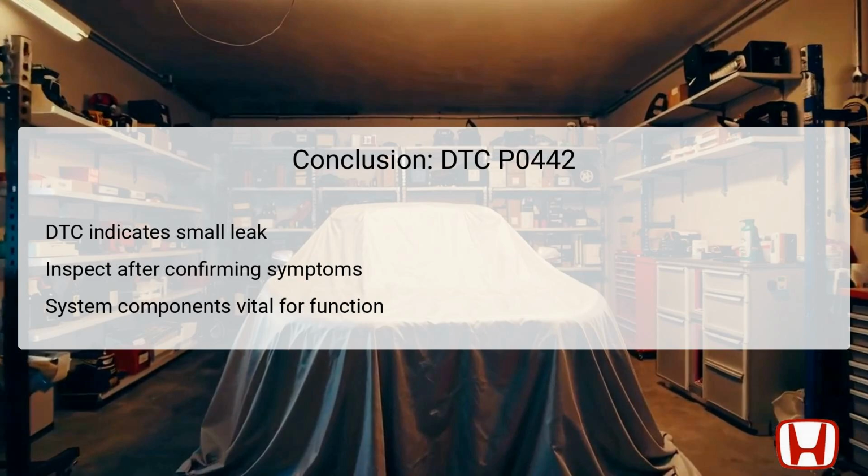Thorough inspections of all relevant components, including the EVAP hoses, valves, and fuel cap, can lead to successful resolution of the DTC. Following methodical troubleshooting steps not only helps repair the leak, but also enhances the understanding of the EVAP system's role in emissions control. Being diligent in addressing these issues promotes both vehicle longevity and adherence to emission standards, confirming the overall health of